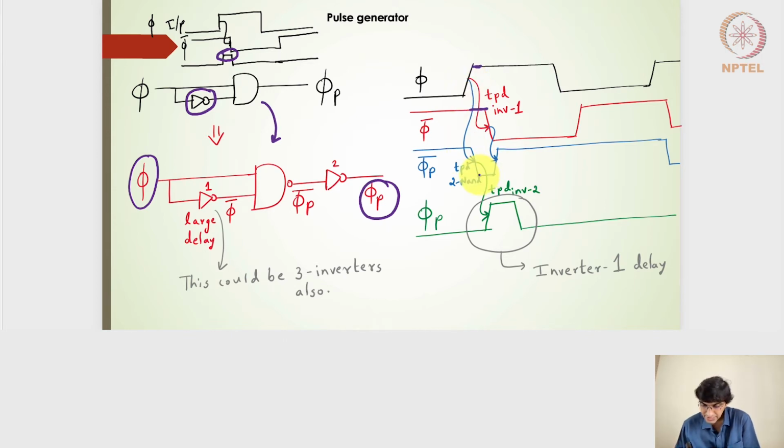So this particular duration is what is generating the clock signal. The output of the inverter here will be nothing but the inverted signal of this phi bar signal. So we'll get the pulse signal here, and the delay in generating the pulse signal from the pulse bar signal will be nothing but the delay of this particular inverter, which is stated as TPD inverter of 2.